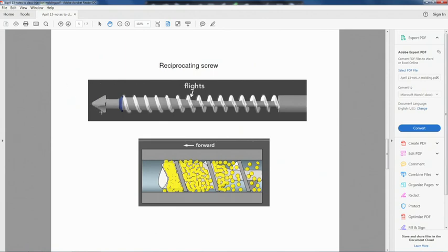If you look at the diameter of the shaft, the diameter is smaller here and bigger here. So as you go towards the injection chamber, which is somewhere here, this diameter goes up. So there will be more effective shearing as you go from this side to this side.